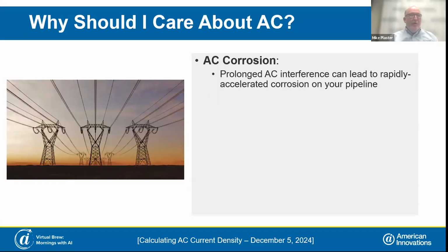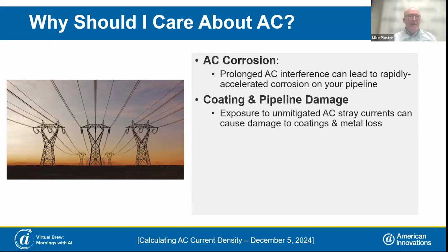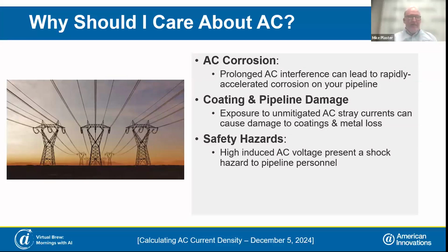All right, so why should we care about AC? Well, prolonged AC interference will rapidly accelerate corrosion on your pipeline. Exposure to unmitigated AC currents can cause damage to coatings and metal loss. And then high induced AC voltage presents a shock hazard to pipeline personnel.